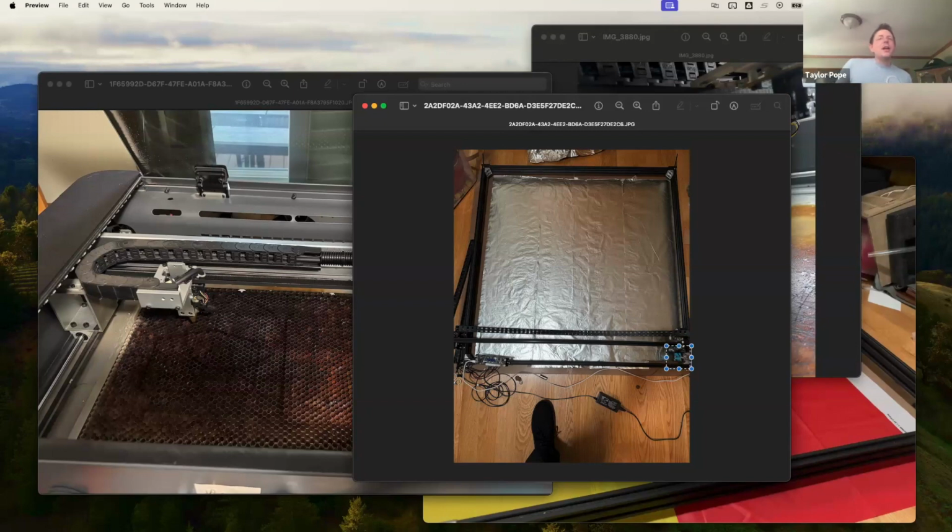When you are dealing with a laser, it is likely going to be based either on a gantry with an X and a Y axis and belts and wheels moving, as both of the lasers that I have, or on a galvanometer, galvo for short. Most fiber lasers are galvo based, which means that instead of having the XY axis that moves either the mirror setup or the laser itself, you'll have a fixed laser that fires at two different mirrors that use complex math to direct those two mirrors to point the laser in the workspace.